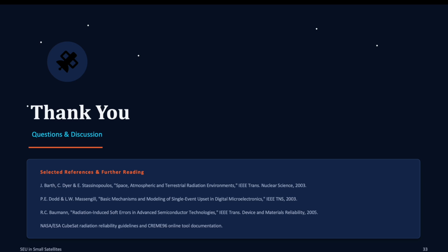Yes. The damage it would cause would still not be permanent damage. I think the question is about solar proton events, and some heavier nuclei. But heavier ions than protons are a very small percentage. In most of the SPEs, it's less than 5% or 1%, and the rest is generally hydrogen ions, that means protons. So those are the ones causing the single events mostly, besides any alpha particles, GCRs.